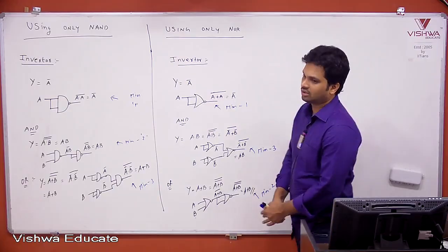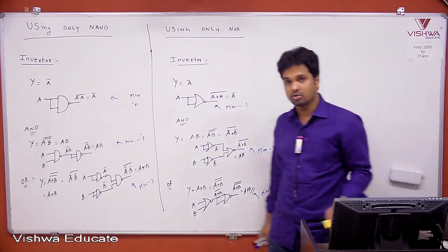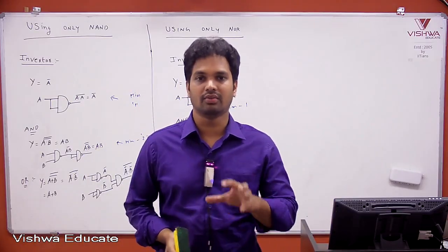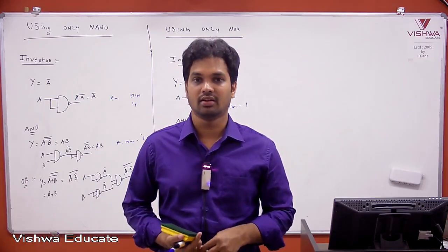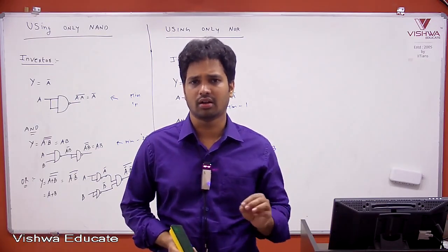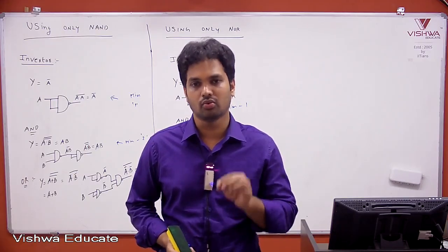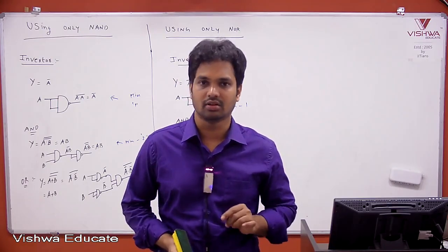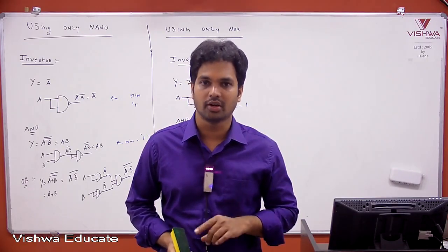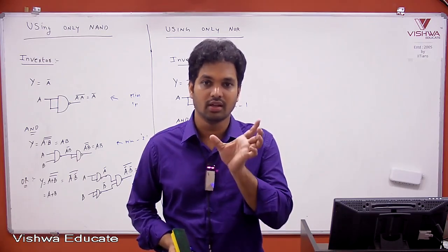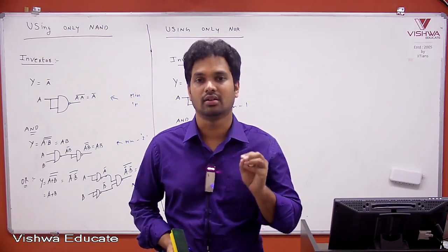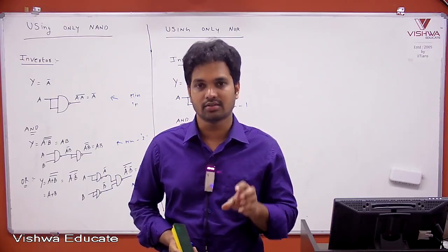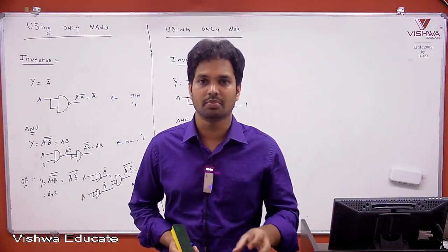Okay? Right. I told you when we discussed Boolean algebra, I have given you a few points. What are they? Other than NAND, NOR, AND, or inversion, XOR, whatever may be, we have 2 functions I have defined. What are the 2 functions I have defined? Implication and inhibition. At that stage also, I told one important point. I will prove it later. I told that implication and inhibition gates are possible. They are called universal gates. Okay, not only NAND and NOR gates. These are also universal gates. What are they? Implication and inhibition.